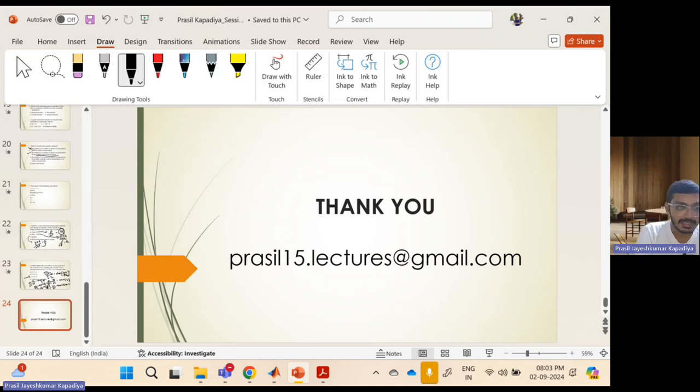So this is all for today's lecture. In today's lecture, we first saw heat transfer through a cylinder. For that we wrote heat balance equations and we solved those heat balance equations using the linsolve command. After that, we did numerical solution of ordinary differential equations using the Euler method. We first saw the theory of how we can derive Euler method's equation. Then we checked RK2 methods and then RK4 methods.